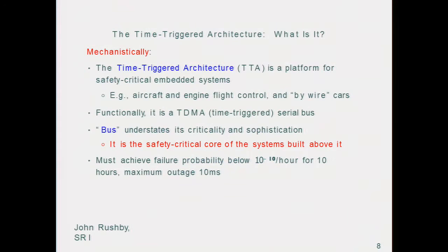Okay. So time trigger architecture, what is it? It is a platform for the design of safety critical systems. And functionally, what it does essentially is that the communication is taken care of through a TDMA scheme. Now, TDMA is time division multiple access. What does that mean? It is something that is known in standard communication.